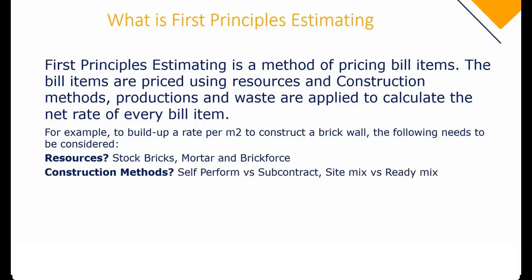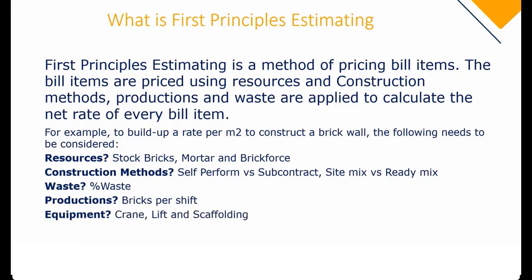What construction methods are you going to be using? Are you going to be self-performing or subcontracting? That also affects what labor force you're going to be utilizing. Is it site mix or ready mix? That will also affect how you build up your rates. Look at how much waste you want to allow. You think about your productions, how many bricks per shift you can lay. You look at the equipment required. Are you going to move material via crane, lift, or are you going to use scaffolding? And you also look at the small tools required: trowels, spirit level, wheelbarrows, and jointers, etc.